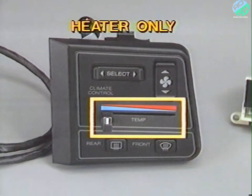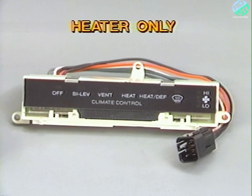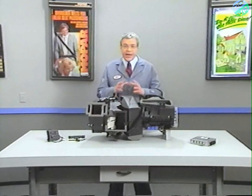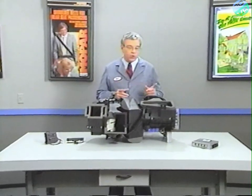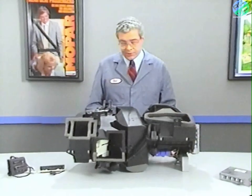The heater-only system uses controls and displays that are slightly different. Instead of a temp switch, a slide lever potentiometer sends a signal to the ACM. In addition, the heater-only display does not have a temperature readout, and of course, it lacks the AC modes found on the displays used on vehicles equipped with AC. All of the switches we've been looking at act as inputs to the air control module, which is located at the far right-hand side of the plenum assembly.